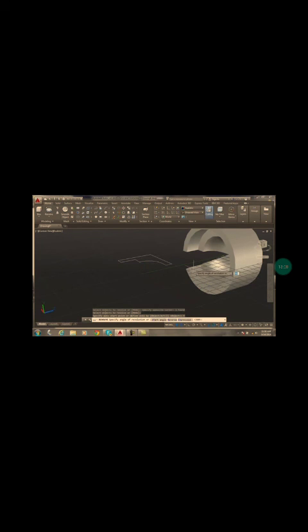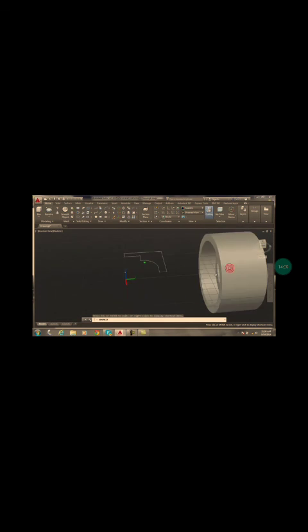hole. Now, if I do the revolve command and I select this item and revolve it around the y-axis, now I'm going to do a 360. There is no hole this time. You can see it's solid, it's filled in. And so I'll undo. You can see that's because the object being revolved touched the axis right there, so it ended up making a solid.